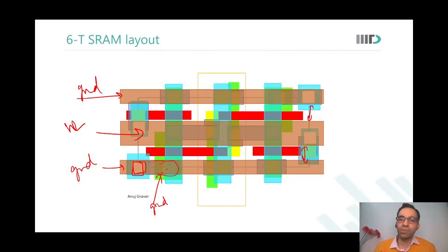But when I do that, what happens? There are two things. First is the word line capacitance increases. This is something I don't like. If the word line capacitance increases, it will rise slowly. It will also consume more power to select a word line and so on. So this is not to my liking. So here we are talking about the Miller capacitance? No, this is metal capacitance, intrametal capacitance. This is M3. This is also M3.